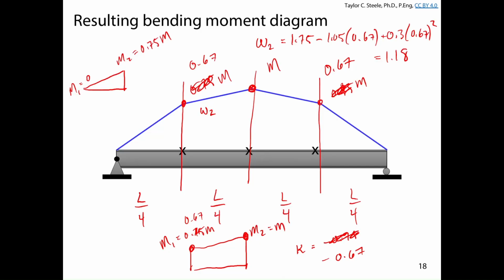Okay, so omega 2 is still a little bit bigger than 1 in this case because it's approaching a constant moment diagram, but it's not equal to the 1.75 that we'd get for the first segment. And so again, for this girder, the moment's bigger in the middle segment, omega 2 is smaller, so the moment resistance is going to be smaller. Moment resistance is lower, factored moment is higher. You should see the pattern here. When you're looking at your girders, the middle segment is going to be the most critical. Okay?